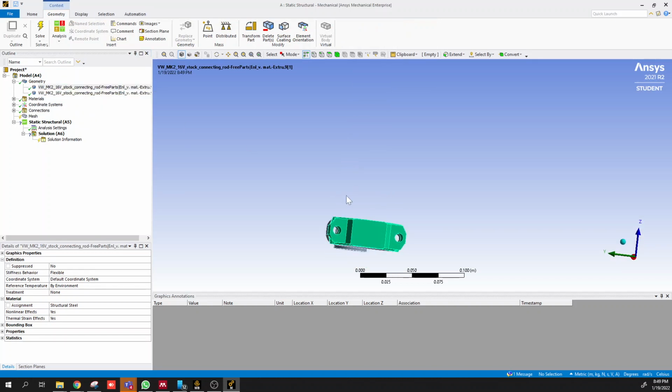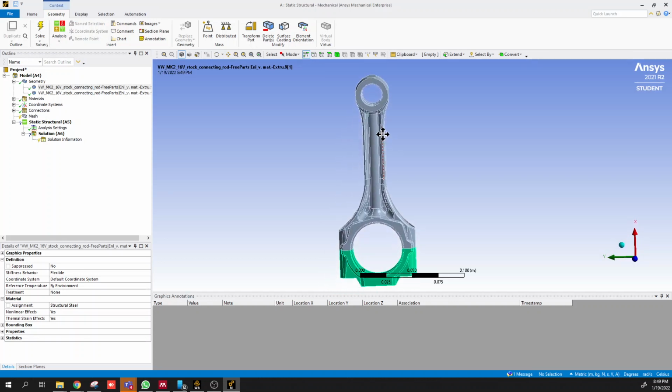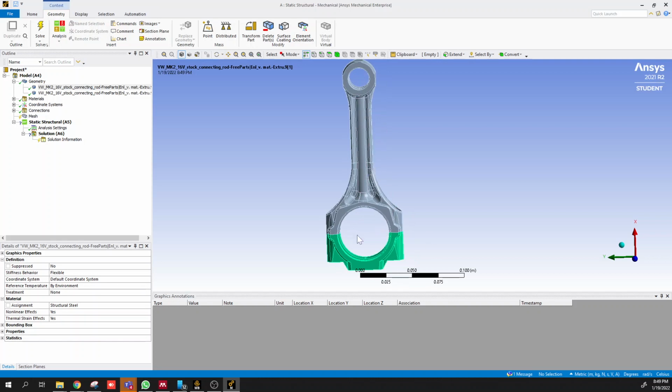Typically it's held together with fasteners, and those bolt forces are preloaded with some applied torque, obviously, to keep these two pieces in contact with one another under the forces of the rotation of the engine, the combustion pressures, and all of those other dynamic things. So we're going to ignore the fact that there are fasteners here. Obviously that would be a much different analysis, and this is just a simplified analysis to look at optimizing the member itself, the section in the middle of the member, for a tensile load case.